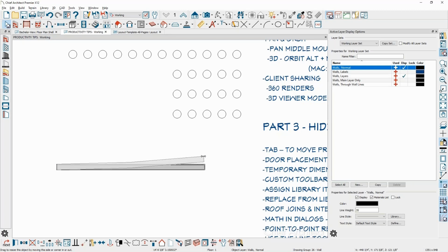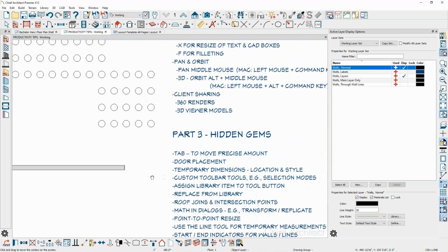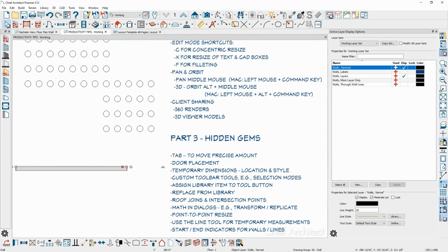We can go on to somebody else and come back to Anne if you'd like. Sure. While you're finding the next person, Anne, if you're able to hear me, the alternate key: press the Alt key, and then I left click. You can curve something. And simultaneously, if you press the Control key down, it will override bumping and snapping, so you can be a lot more precise and curve it in any increment versus the 7.5 degrees.